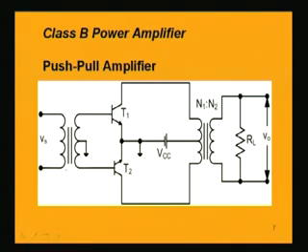If suppose we have N1 here, N2 here in the secondary side, then N2 by 2 will be in this half number of windings and N2 by 2 will be in the secondary lower half. That means exactly equal voltages will be induced in the two halves, and we are considering N1 is to N2, that is the turns ratio in this output stage transformer.